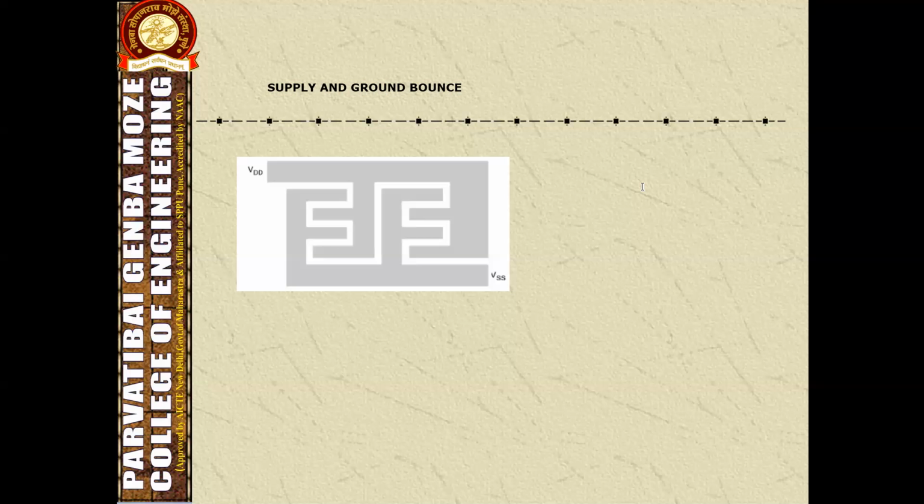Therefore, the designer uses a heavy copper plane, making it as full as possible with as few cuts and holes as possible. But in fact, this inductance in many high-speed circuits is just too large to tolerate.